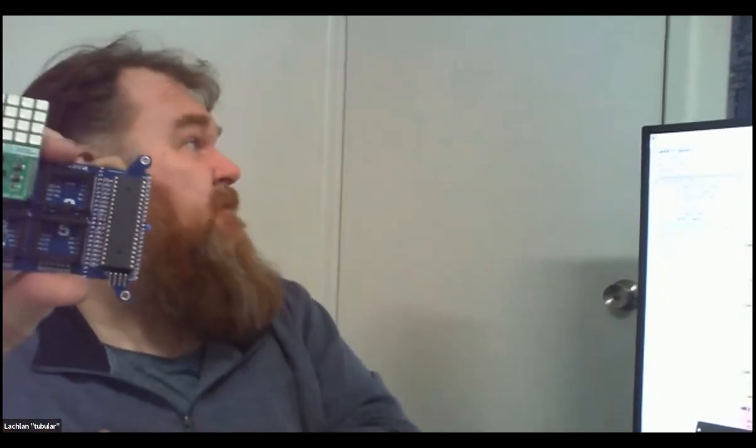The way we did that was you've got your P1 footprint on the inside circle, and we just added a second row of pins around the outside for the P2, like port B, in effect, P32 up to 63 around the outside. And that means we can go back and put that module into our P1 designs, of which there are quite a few.